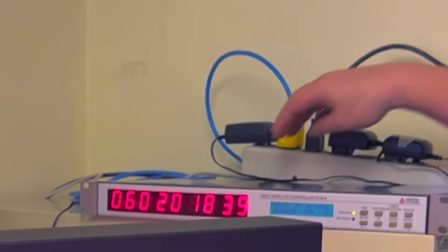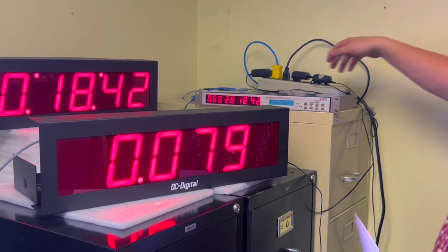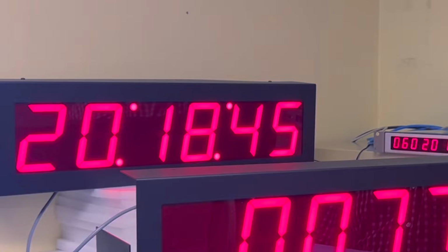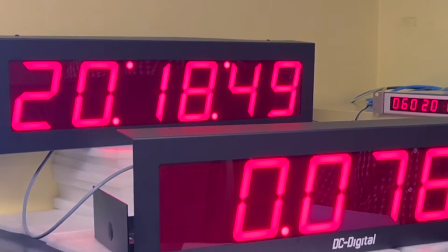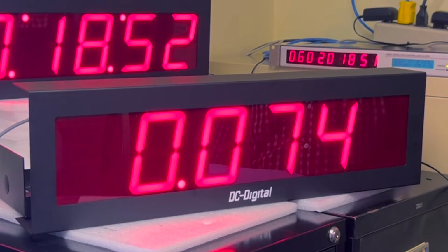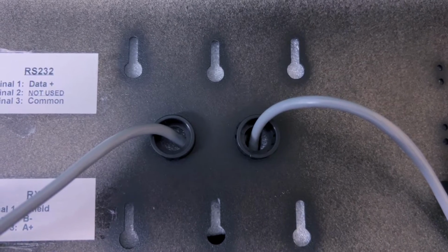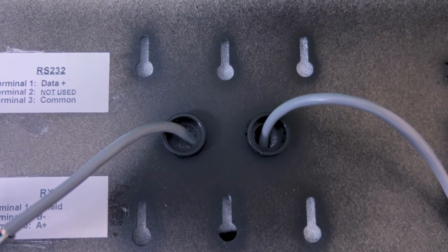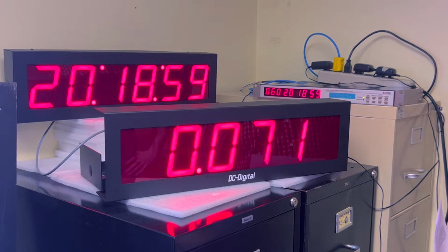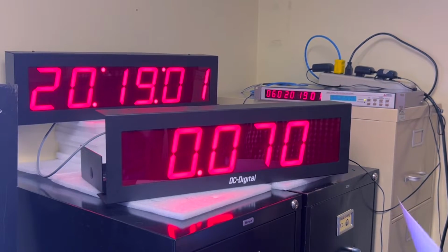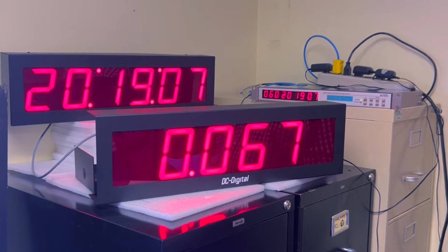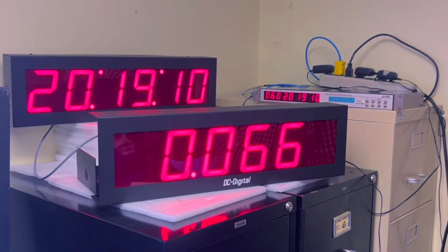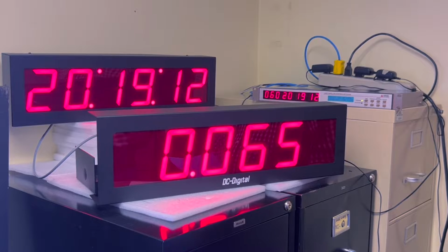This has an RS-232 port out the back of it. That is going into this first display. This display can then send data via RS-485 1200 meters to this display, which could then send this data to another display 1200 meters away, and we could continue on indefinitely. This specific model covers 232 in only, 485 in and 485 out. So we will make it that way.